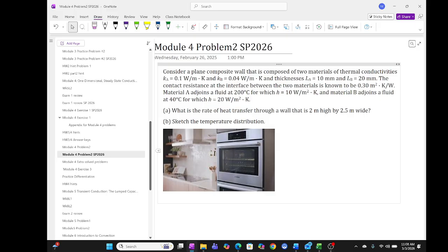Like in an electrical circuit, Ohm's law. Everybody remember Ohm's law? Ohm's law is like V = IR. The R is the same, electrical and what? Heat transfer. But this V is equivalent to what? Delta T. Very good. And this I is obviously the missing component Q, right? The Q. Okay. So that's for the series resistance.